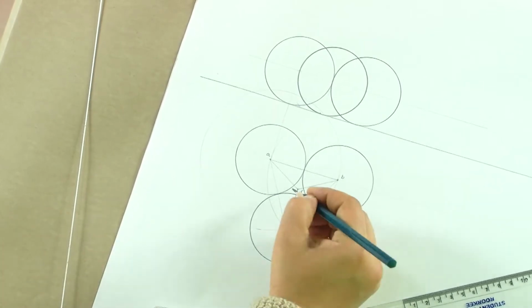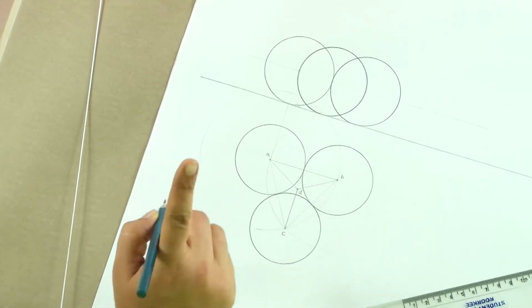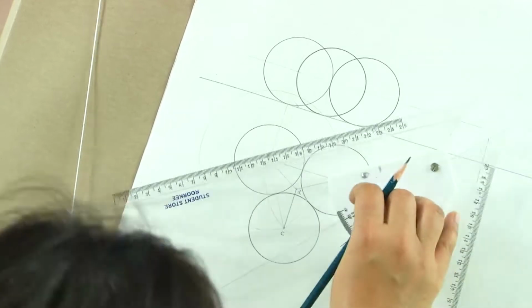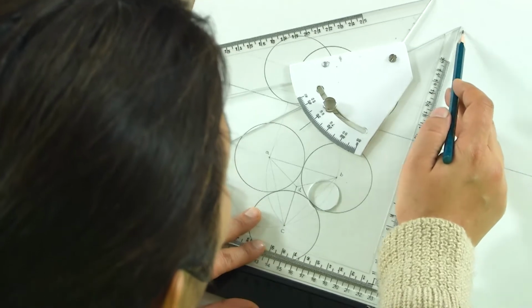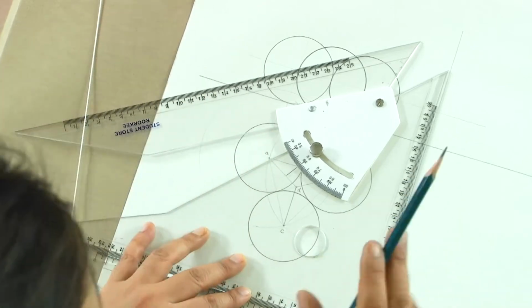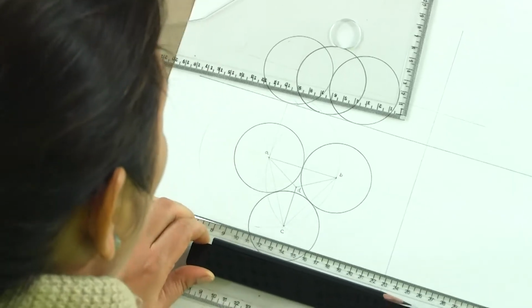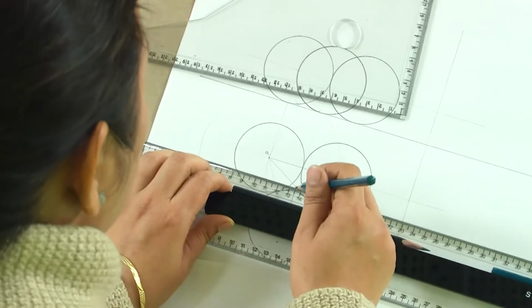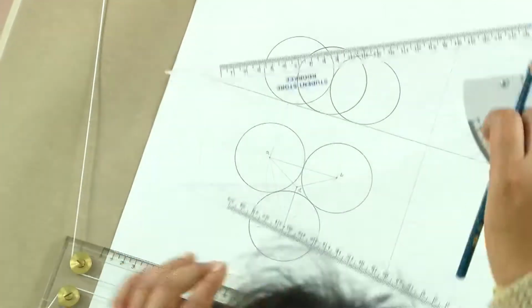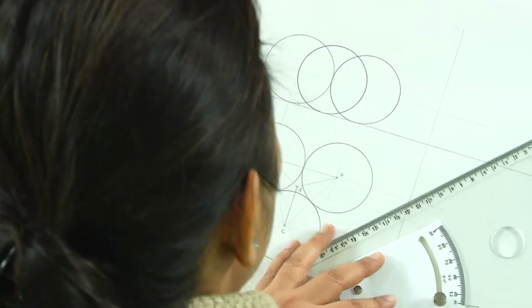The only line which is this DC, it is making an angle with both HP and VP, but we have the side plane to which it is going to be perpendicular. So all we have to do is take this line DC onto the side plane. So, just like we did earlier, we will project it onto the side plane.